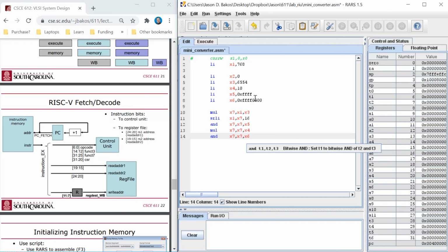Now you might be thinking, wait a second. Why do you have to mask off the fractional bits? Because if you had 0.8 and multiplied it by 10, you should get 8.0 with no fractional part. That is true, except remember that the 0.1 wasn't exactly 0.1, because when we divided 65,536 by 10, we had to round up to 6,554.